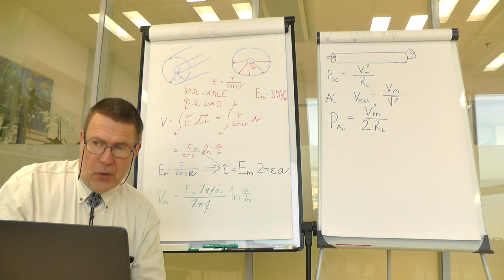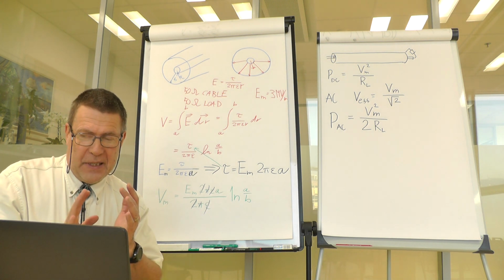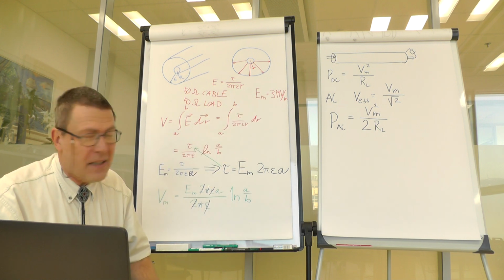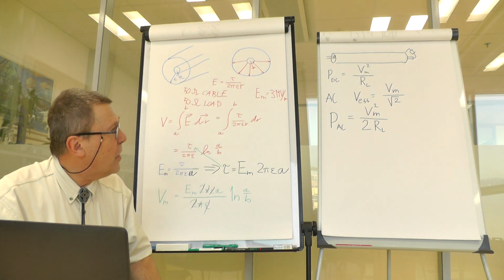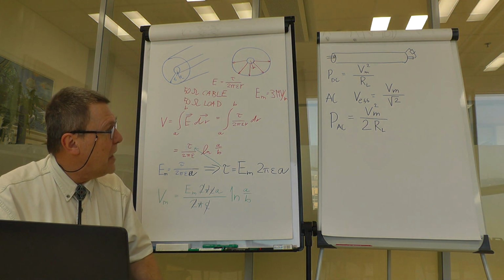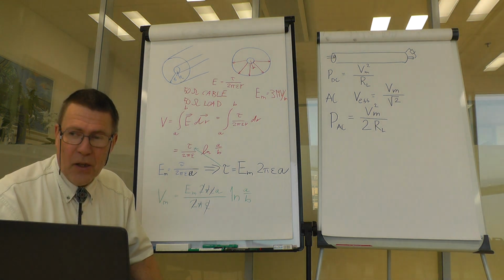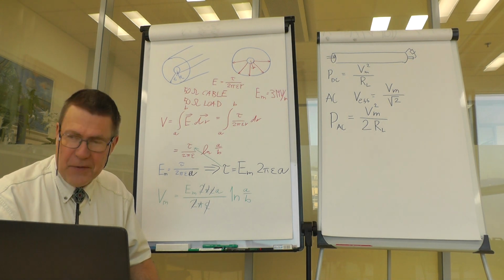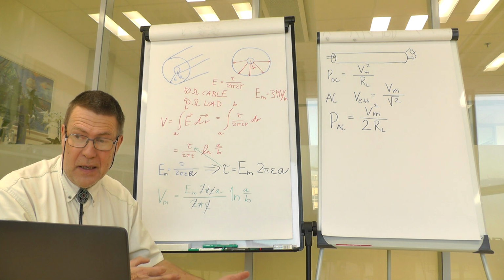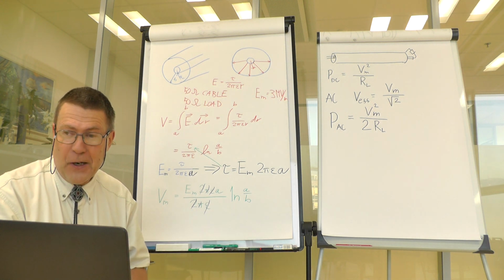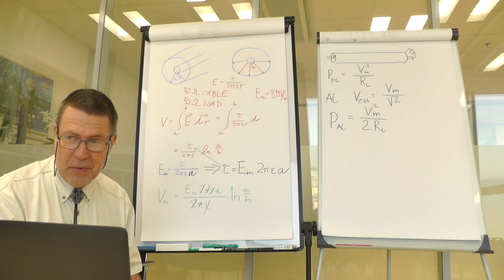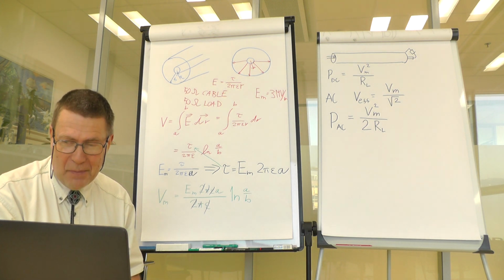Let us continue. So we had first a DC transmission, which we have established on the right panel. Then we have an AC low frequency transmission, and we have seen that the maximum power handling capability to the same load has been decreased by a factor of 2. And now let's have a high frequency transmission where standing waves might happen.